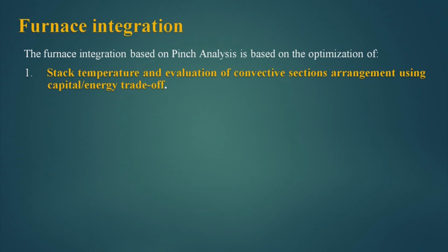Now, this furnace needs to be integrated with the process. When we integrate the furnace to the process, two major optimization problems appear. The furnace integration based on pinch analysis is based on optimization of stack temperature and evaluation of convective section arrangement using capital and energy trade off. When the furnace is integrated, we have to find out what should be the stack temperature.